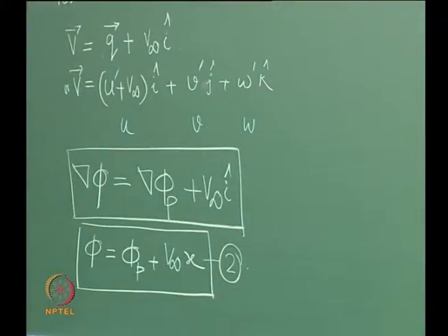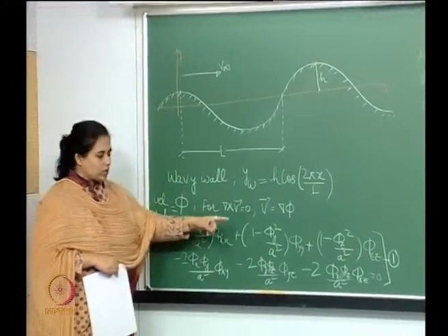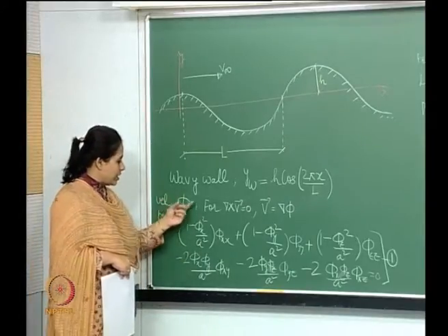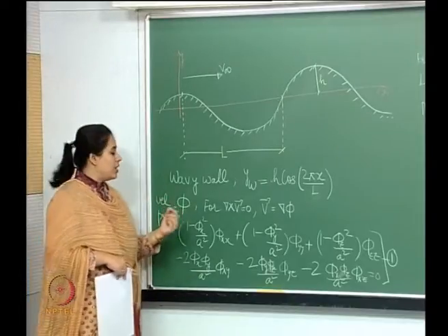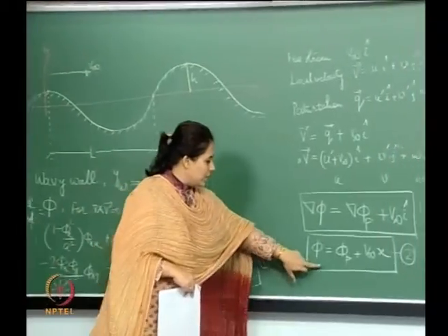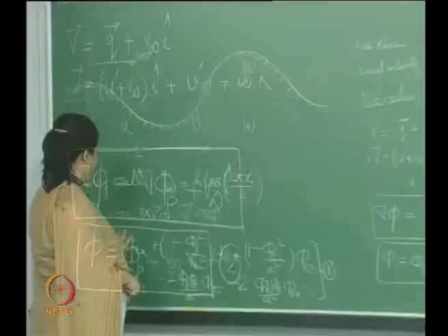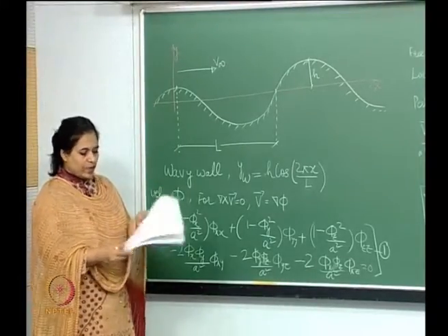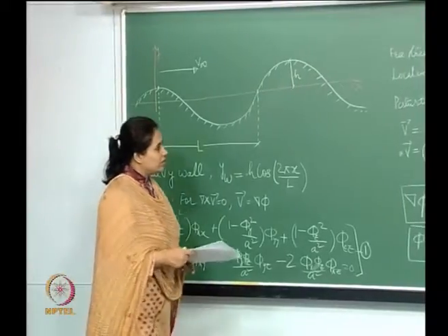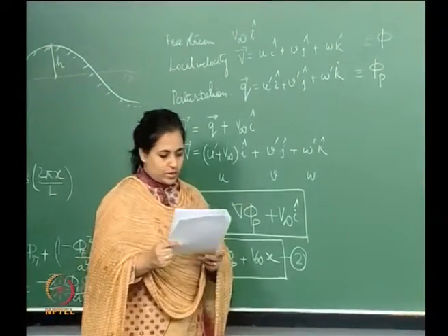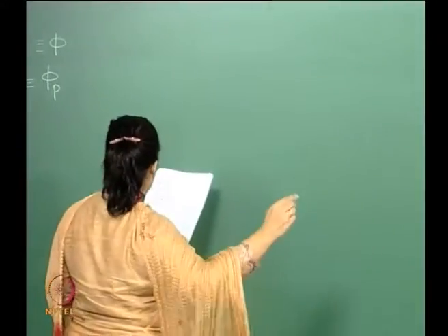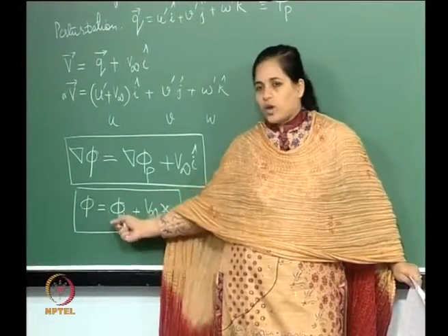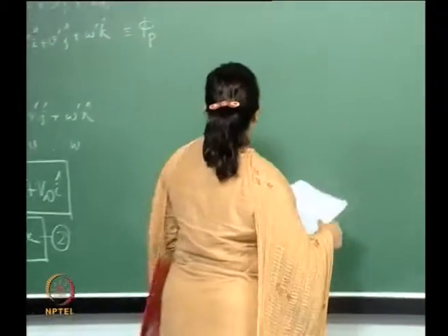So you see this is the velocity potential, and correspondingly this is the velocity potential equation. We said that using perturbation theory, we are able to write this potential as a free stream potential plus a perturbation potential, which is what we derived in this particular equation. Now we will use this equation in equation 1 and see what we get. It is almost a half page equation, but I will write it out, just to scare you, and then we will see what to do with it. It is important to write this. I am using the surface potential equation into the velocity potential equation.